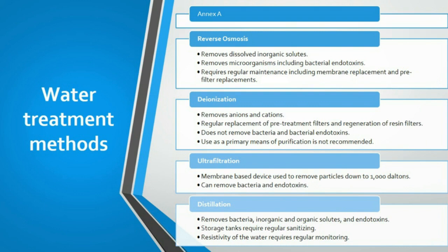Now we're going to talk about DI. That removes anions and cations. It requires regular replacement of the pre-treatment filter and regeneration of resin filters. It does not remove bacteria or bacterial endotoxins. That's not what DI does. Use as a primary means of purification is not recommended, because of the endotoxins.